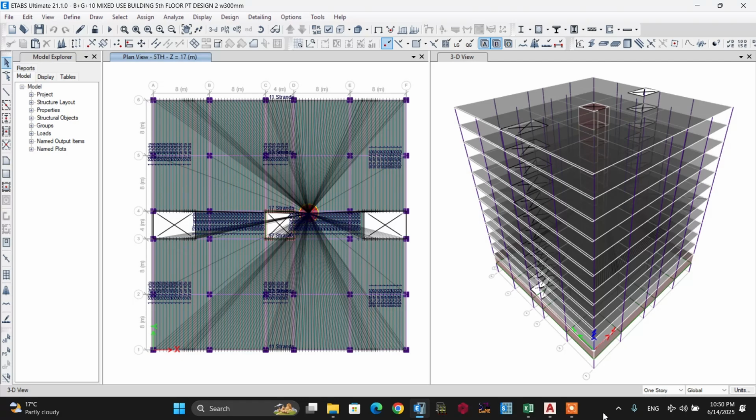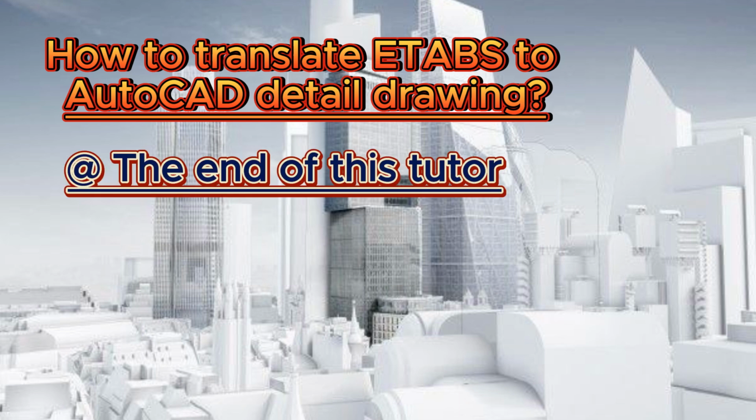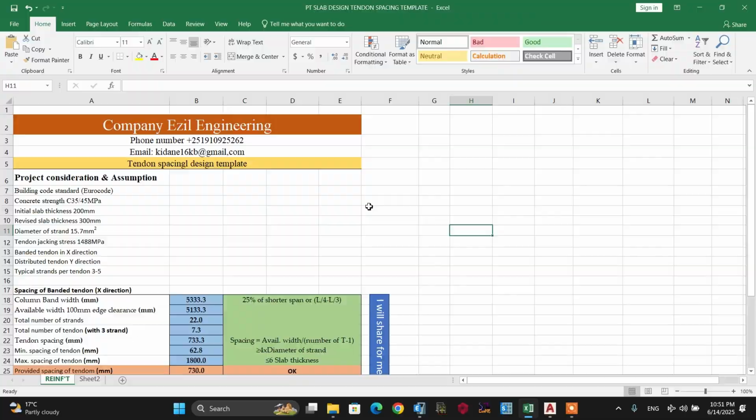Today's tutorial is all about how to translate CSI ETABS analysis and design output into a constructible AutoCAD detailed drawing using an Excel design template and the AutoCAD program. At the end of this tutorial, you will know exactly how to calculate banded and distributed tendon spacing, how to decide the number of strands within a tendon, and the tendon profile. This is the Excel design template to calculate the spacing of banded and distributed tendons in the X and Y directions respectively.